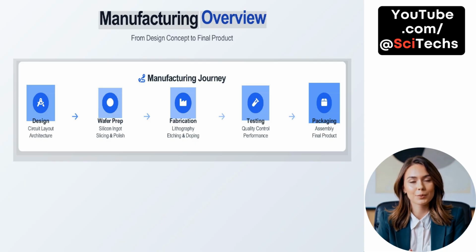Next comes wafer preparation. Here, pure silicon ingots are sliced into thin wafers and then polished to create a smooth, defect-free surface, ready for micro-scale processing. The third phase is fabrication, where the real magic happens. Using advanced techniques like lithography, etching, and doping, we form intricate circuit patterns and build the transistor structures layer by layer.